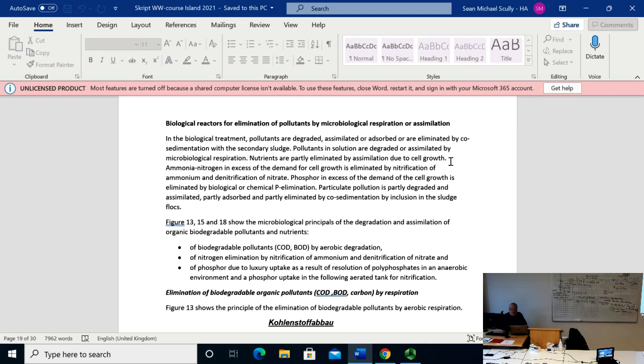30. And out of these 30, because those proteins are almost exclusively in particulate matter, and from the particulates, 70% you get by sedimentation. So from those 30%, 70% makes 21%. They will be in the primary sludge. And 9% will be particulate in the filterable matter, and will be in the inflow to the biological reactors.